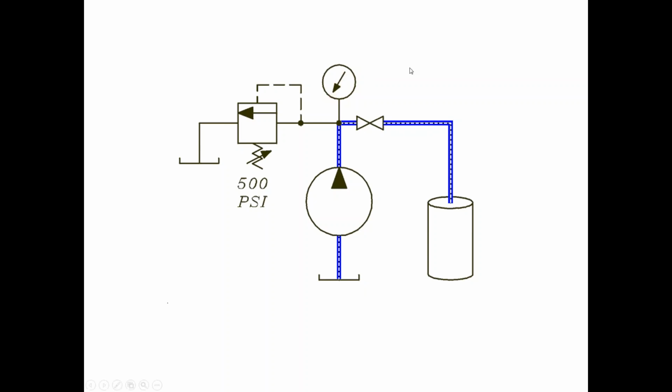Right, well, does that mean I need to change my pump? Well, of course not. However, how many times have you seen a pump change for no other reason than because the pressure was low? I personally have seen it hundreds of times. But the reading on the gauge in and of itself is no indication whatsoever of the condition of that pump. You need some other reason to change a pump.